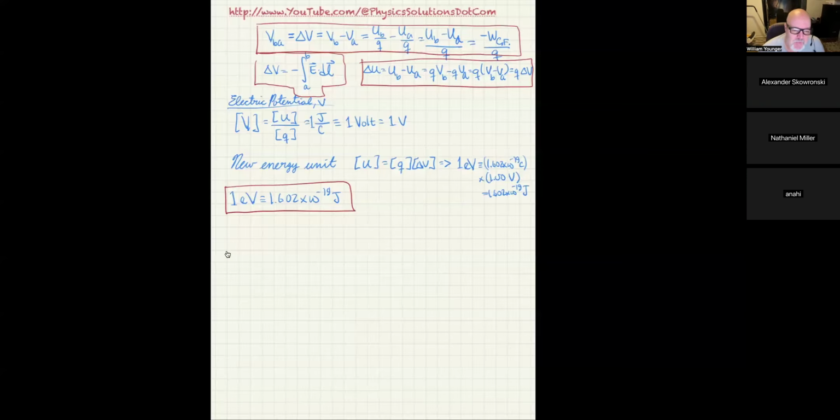The automobile battery, like we said, is 12 volts. AA, AAA, C and D batteries are all 1.5 volts. That's their nominal voltage. But when you actually buy them, it's much more typical that they might read 1.72, maybe down to 1.68. That's normally what they start off as. As they get more and more used, it's almost as if they have some internal resistance, so that the terminal voltage drops from 1.72 down to 1.65, down to 1.6, 1.58, 1.55, and even down to 1.5.